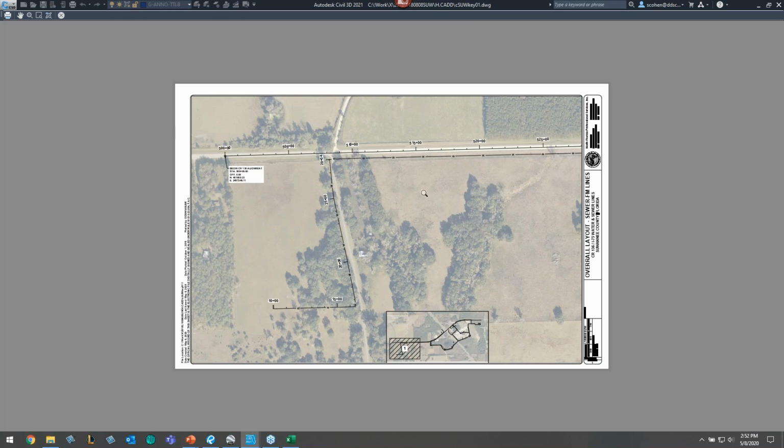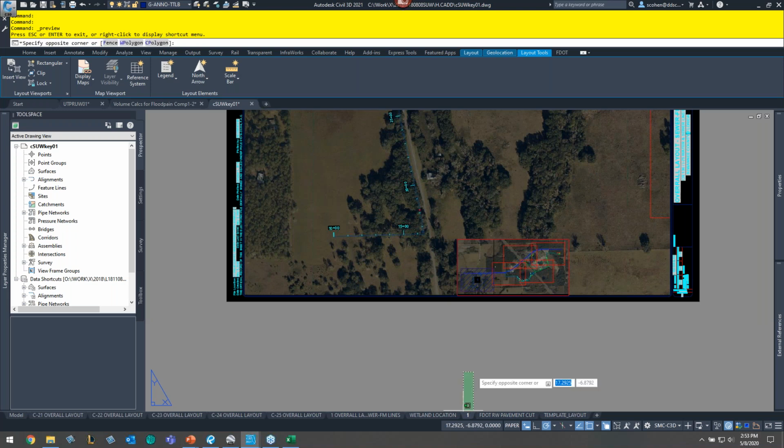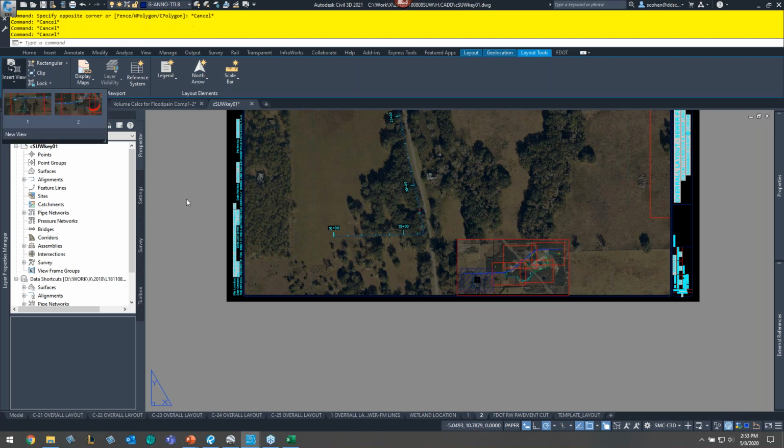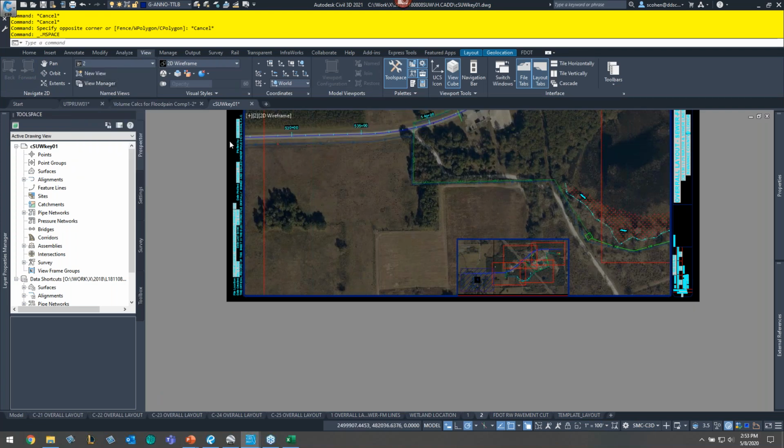In fact, just to show that to you, because it's really not hard, I'll go over here and I'll go ahead and just copy this. I'll hold the control key down, drag this. We'll click on this, drag. Now I have another viewport. Let's make that active. I'll type number 2. And although before I used the insert view option right here, you don't have to do that here. In this case, I'm going to double click inside this, unlock the viewport, and change this right here. Go to the view tab and click 2. I'm done. That's how simple this is.